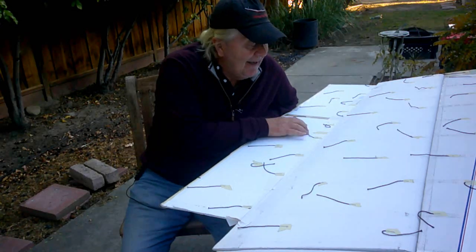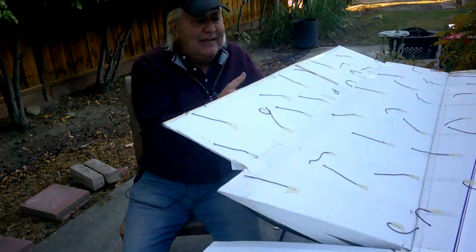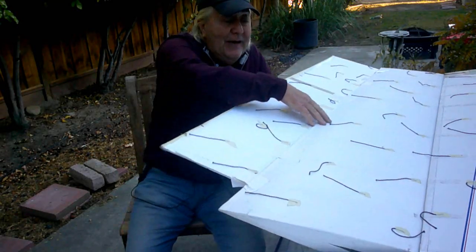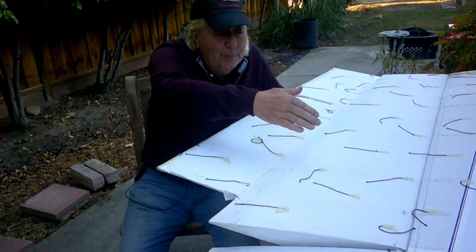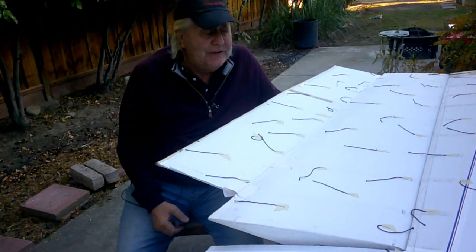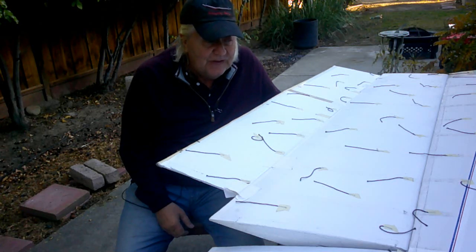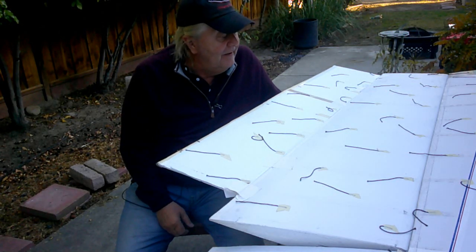We're back to this thing that I have tacked on here. And what this is, is a 9-inch extension on the back of the elevon here to bring my chord up to 33 inches and increase my Reynolds number up to 500,000. And darned if it doesn't work.